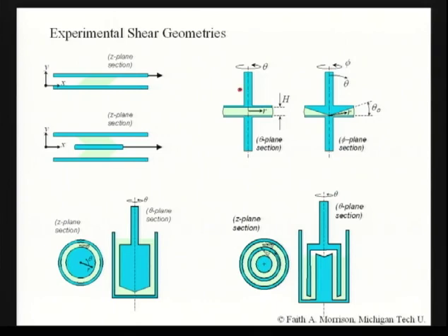In the book, I talk about this flow, parallel plate flow. That's another very common shear geometry. And then a modification of the Couette geometry that produces more torque is the double-walled Couette. So this one, as it turns, will produce more torque because there's fluid on both sides. And so for a low viscosity fluid, that produces a higher signal.